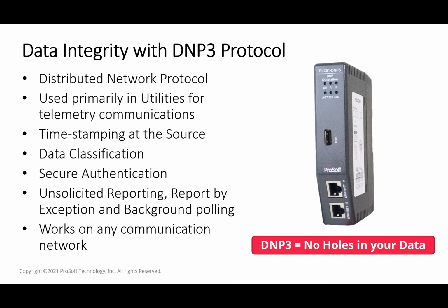And the advantage of all of that is you can bring back information in groups or as required, with the most critical being always available to ensure, again, you've got a complete and current view of the system, but then you're not missing out on anything, let's say, that happened between communications, for example, where a level might have changed or a tank might have gone faulty on and off. You can capture all of that. So really with DNP3, you can be ensured that there's no holes in your data.